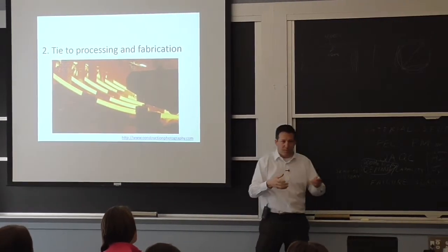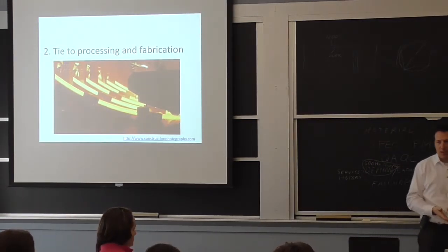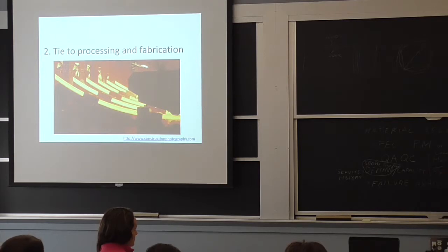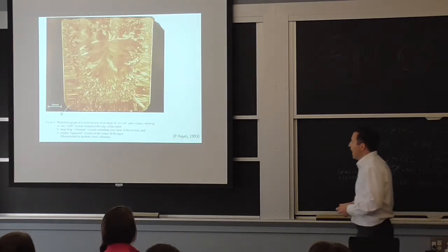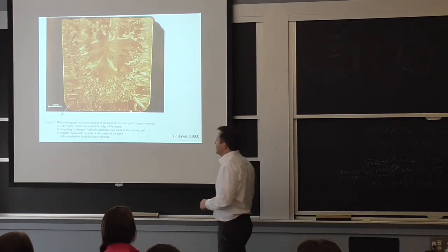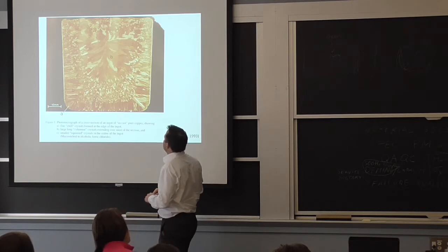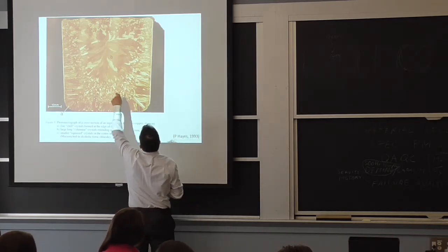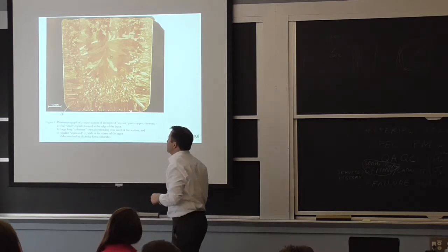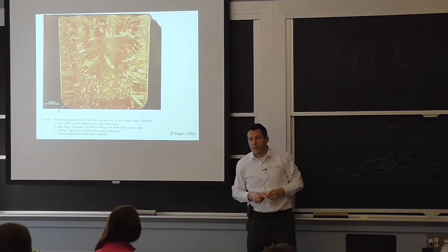You start with making a big piece that you cast, and then you keep deforming it and deforming it. Now, what is the reason why you deform it? As cast, the metal alloys have a lot of heterogeneity. You have a very different grain structure between the surface and the very core. You also have some differences in chemical concentration.